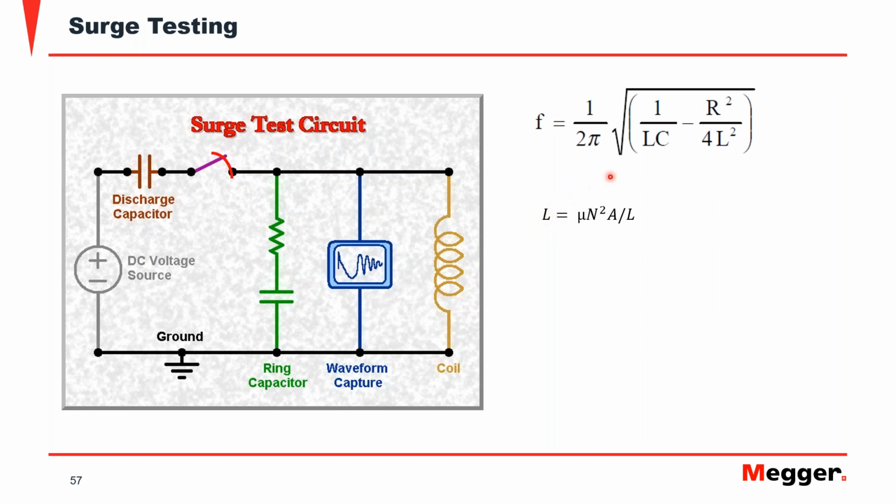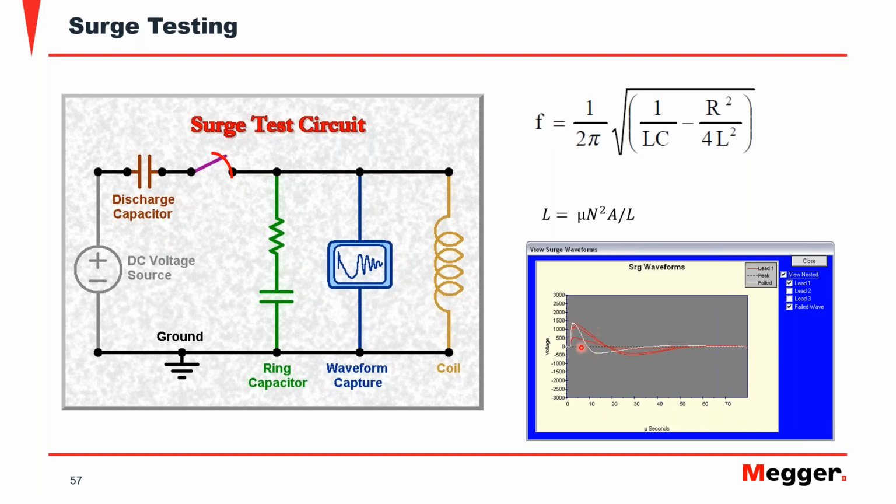And when the inductance drops, see how we have an inverse relationship between the frequency and the inductance. So as the inductance drops, the frequency is going to increase. And we can measure that. We can determine how much that waveform has changed when one or more of those turns were shorted by the effect of the increase in voltage that we are applying to the coil.